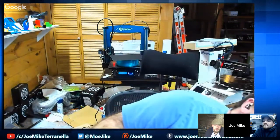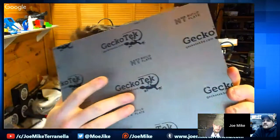The only thing I am not entirely thrilled about with Gecko-Tech is the longevity of it. The reason I can't use this one very much anymore is, you can't really see it on the camera, but parts of the coating have actually peeled off with prints. My very first nylon print on my FlashForge took the coating off of it.